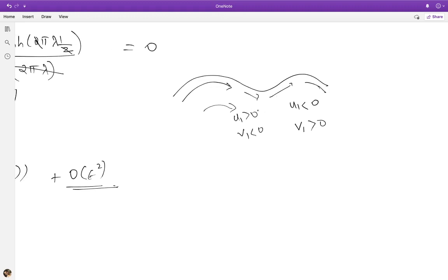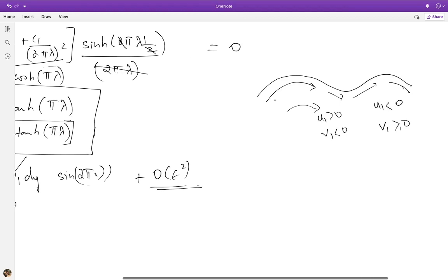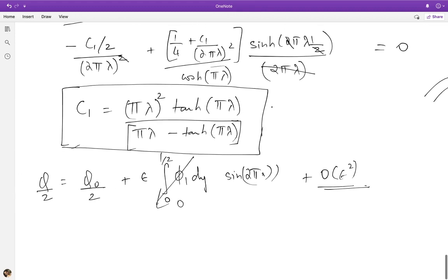However, you should make sure that these negative and positive pressure gradients are only the perturbed pressure for small epsilon. The overall pressure is these pressure gradients plus g, which is a significantly order 1 constant. Therefore, the overall pressure, if you measure with a manometer, is always falling down the channel. It never increases along the flow, which makes sense because for a creeping flow, you cannot have flow into an adverse pressure gradient. It has to constantly be decreasing because it's the only source of momentum. You have no inertia to overcome adverse pressure gradients as you do in non-creeping flow cases.